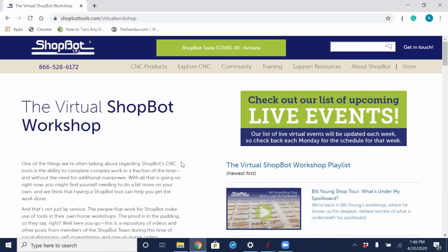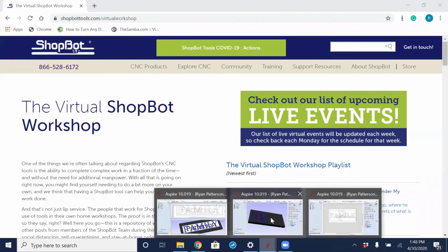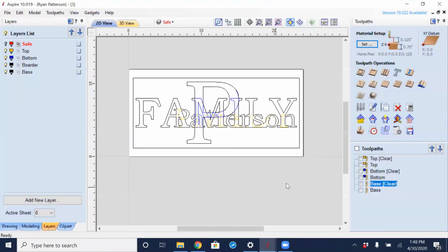So yeah, inside corners or getting a clean edge on your text, to see what it's really about, detail and what bit diameters you have. You can't ever get a square inside corner. That's not going to happen. A couple things that you can do that might help. One is V carving. V carving on stacked text and layers like this is difficult. You really can't quite do it unless you do the top layer.